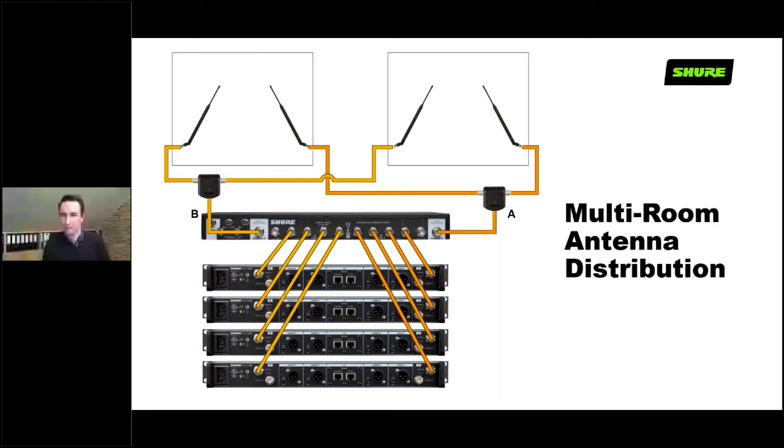So essentially, you've got an A and a B in zone A and an A and a B in zone B. And those are going to now be pushed through the DA. This is a simple way to achieve a 2-zone receive system, using distribution and looks like ULXD, and kind of the most basic way to get a multi-zone system in this setup here.